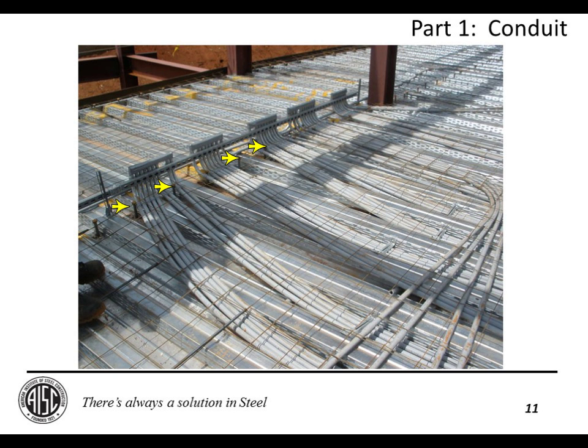Hopefully you don't get to this point, but there are situations where you need to have conduit within your slab for all sorts of different reasons. So what amount of conduit is reasonable? What can you tell the contractor is okay? And then in conditions where you do have to bundle some conduit, what can you do about it? All right, so the first thing I want to take a look at is, are there any actual codes and specifications that address this particular situation?